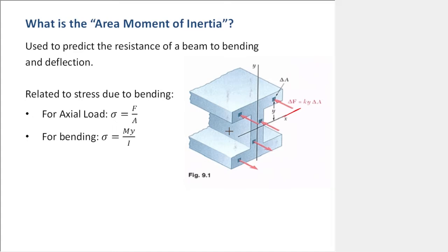The stress in a beam, which we haven't really talked about too much, but you learn about stress in mechanics and materials. Stress is force over area. So far, we've just been studying force. But if you think of all of your bridges, what we really care about is how much stress there is in each one of these members. It should be intuitive that a larger member could hold more force, and a smaller member can hold less force, right? So if we just look at the force, we're not learning a whole lot. If we look at the force divided by the cross-sectional area, that's telling us how much that beam is feeling stressed. So stress is really the measurement of whether this thing is going to fail or not.